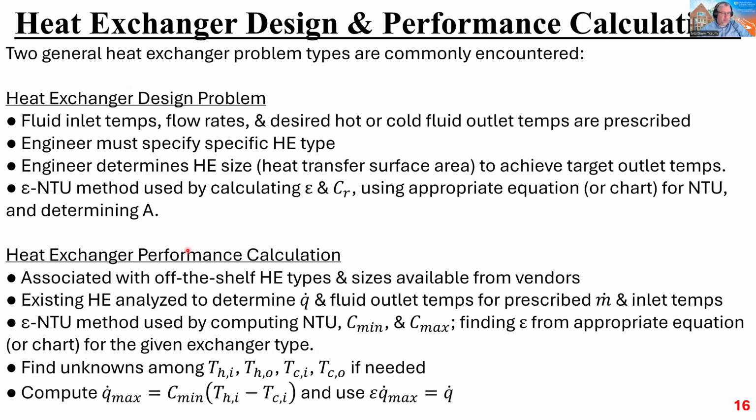So heat exchanger performance calculations. This is a situation where you've got an off-the-shelf heat exchanger that comes from a vendor, and you're trying to evaluate whether it is going to meet your requirements. So you're analyzing an existing heat exchanger to determine its heat transfer and fluid outlet temperatures for a prescribed set of inlet conditions, so inlet temperatures and mass flow rates of hot fluid and cold fluid.